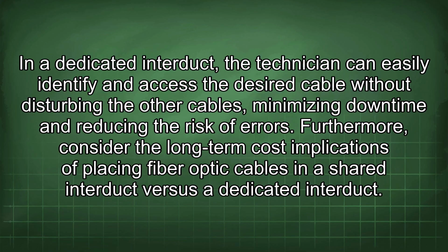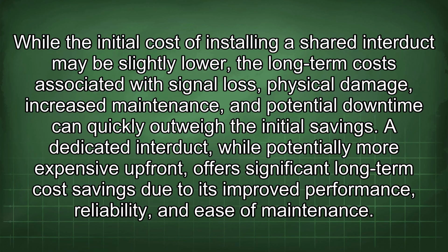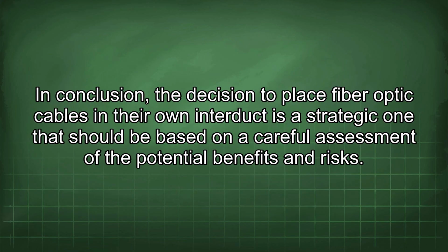Furthermore, consider the long-term cost implications of placing fiber optic cables in a shared interduct versus a dedicated interduct. While the initial cost of installing a shared interduct may be slightly lower, the long-term costs associated with signal loss, physical damage, increased maintenance, and potential downtime can quickly outweigh the initial savings. A dedicated interduct, while potentially more expensive upfront, offers significant long-term cost savings due to its improved performance, reliability, and ease of maintenance.